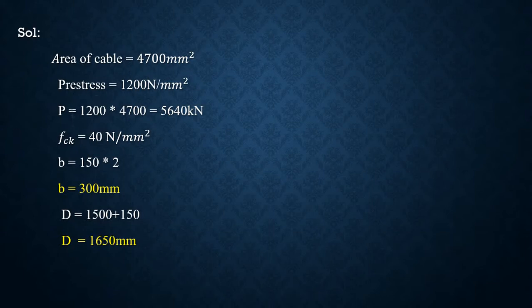Next is pre-stressing force. This is initial pre-stress. The pre-stressing force is stress into area of the cable. Stress is 1200 into area of the cable is 4700. That will give you the pre-stressing force as 5640 kilonewton.